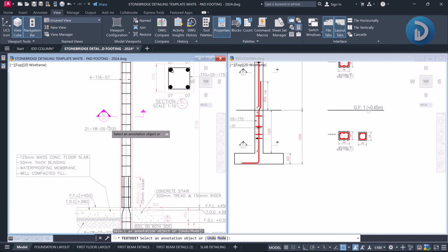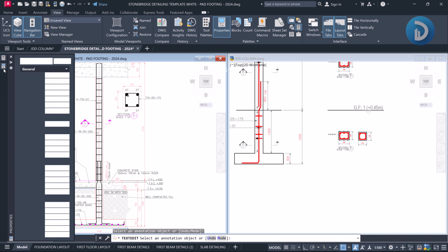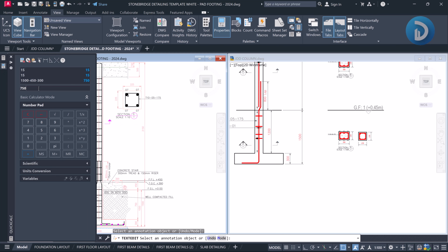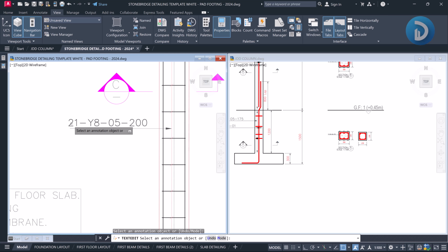But if we intend to get the total numbers of reinforcement, it means we have to divide 3.15. You have to divide 3.3150 by 200. Okay, so in this case we are having 16 numbers of reinforcement. So it means this will change from 21 numbers to 16 numbers.